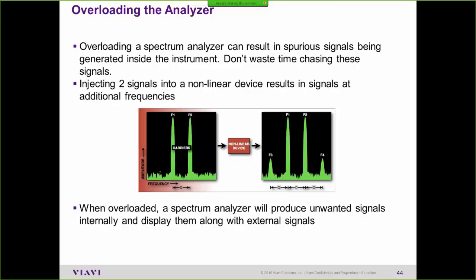Well, every 6 dB you can push down that displayed average noise floor doubles the distance at which you can see something. So if I'm hunting for interference, and I can see it when I'm right on top of it, 10 feet away, with my displayed average noise level in the analyzer at -100 dBm.